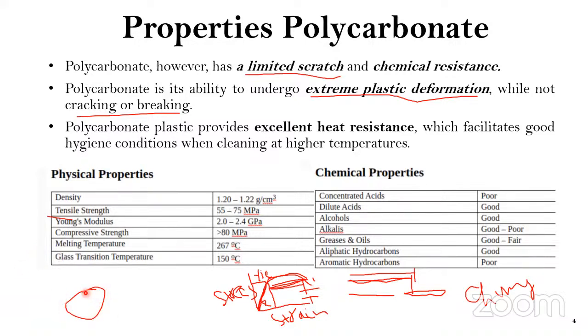So that petri dish is also manufactured from polycarbonate material, because we need to sterilize them around 105 to 120 degrees Celsius, so that no external microorganism can attack there. Only the microbes I want to grow, only those I can grow. So the sterilization process in the bio or medical field is quite important, and that is the reason they use polycarbonate, which has quite excellent heat resistance.